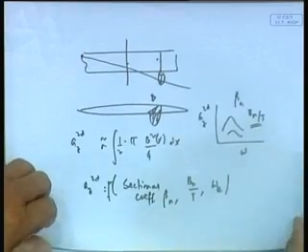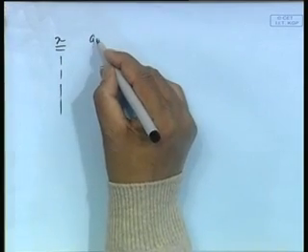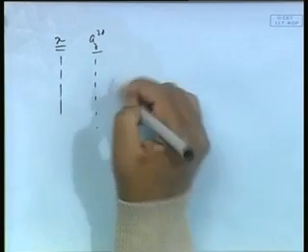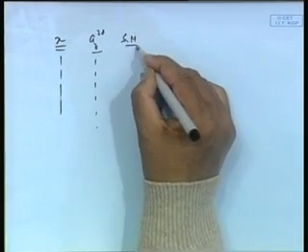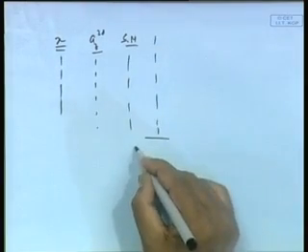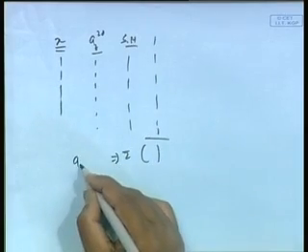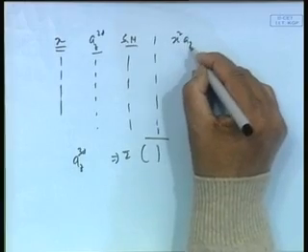Very simple. You simply make a typical hydrostatic type table. I have got x stations here. I end up getting these Az 2Ds. Then if I want to use Simpson's multiplier, I get this one, and by summing I end up getting here Az 3d, and here I use x square into Az 2d.